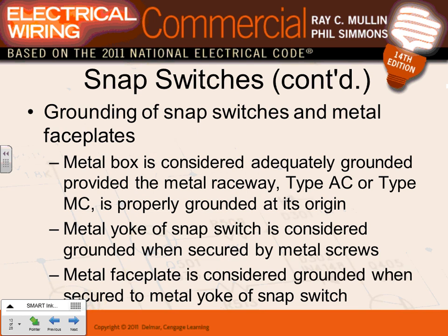The receptacle that you're looking at, the frame of the receptacle had to be grounded. As of 1999, I believe, they started grounding it. The box has to be grounded, and the cover, if it's non-metallic, doesn't have to be, but if it's metallic, the screws right here that go through the cover will ground the cover. So there are three things you need to ground for the receptacle.